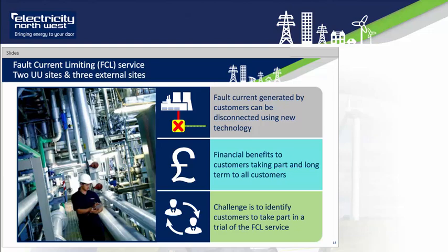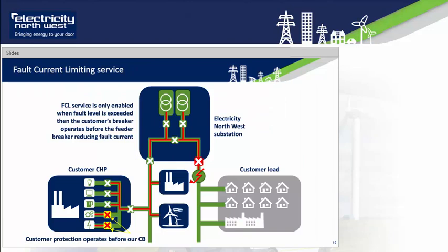As an example, electricity flows through the 2 transformers to the factory on the left and the homes and businesses on the right. At the factory, different types of equipment are connected to the network, including a large motor and a large generator. A fault occurs, the red squiggly line again, and the fault current rushes towards the point of the fault. All protected devices start to operate, but the closest one to the fault operates first and disconnects the customers on the network beyond the fault.